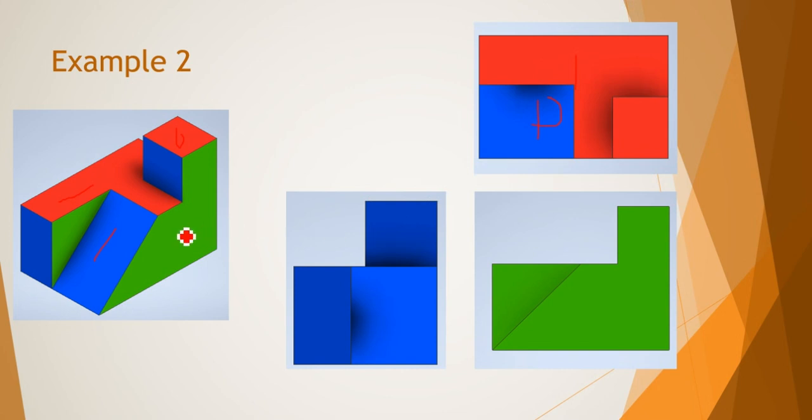and the front, this will be the front, all these that are marked green, as you can see, and these blue faces will make our end elevation. So as you can see here, the end elevation, the blue face, is on the left of the screen, so it will be on the left side of the front elevation as shown in our example here.